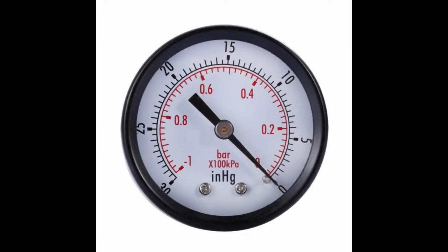This is a vacuum gauge to show that this needle will move close to the end, or 98.5% of what was shown in the previous example, which is actually a very easy vacuum to achieve. It is only in the high vacuum range, past 100 microns, that it begins to be hard to achieve vacuums at that range, which is above 99.99% vacuum.